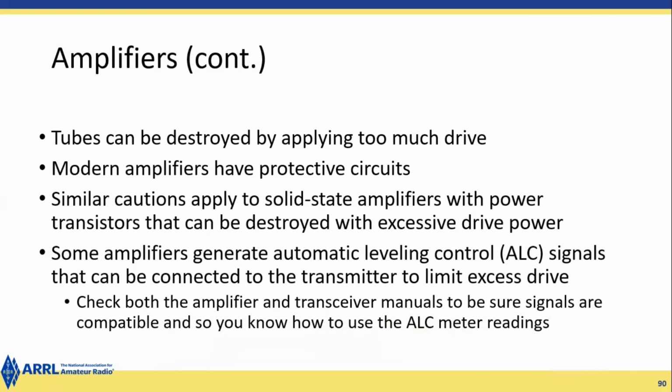Some amplifiers generate automatic level control signals that can be connected back to the transmitter to limit excess drive. Check both the amplifier and the transceiver manuals to be sure that they're compatible signals, so you know how to use the ALC meter reading. So that's important. It's pretty standard, but you need it. Sometimes there's a nuance there. You've got to go check that out.